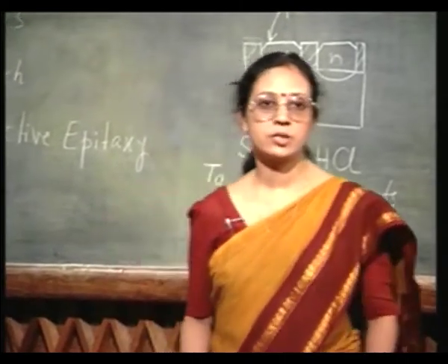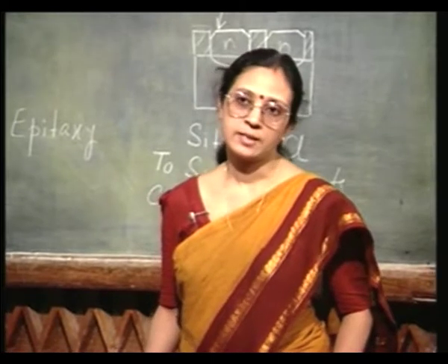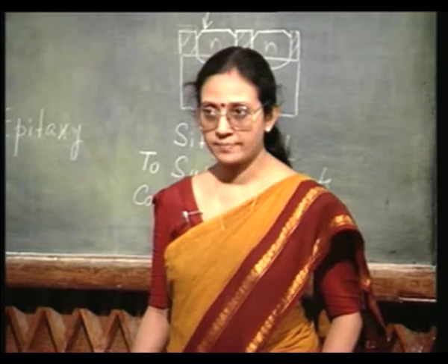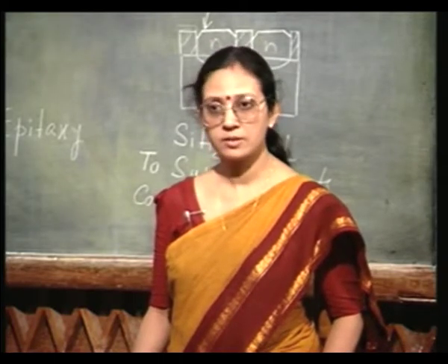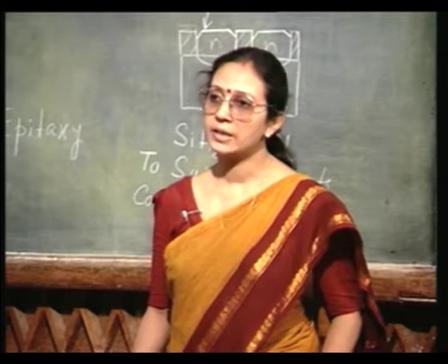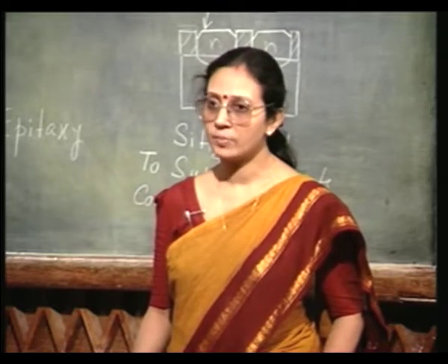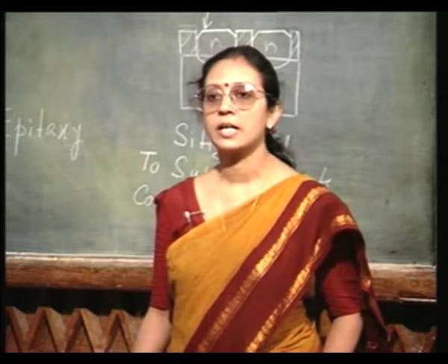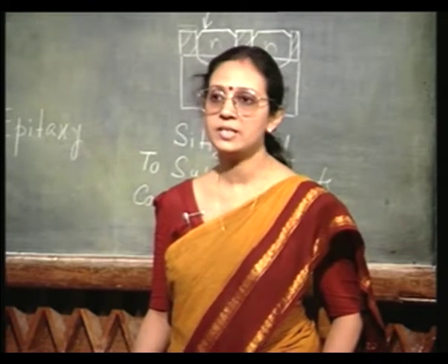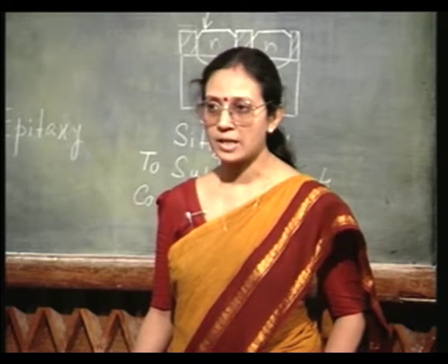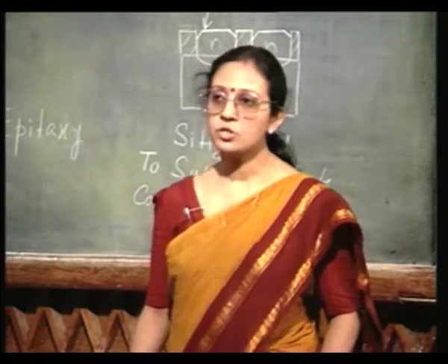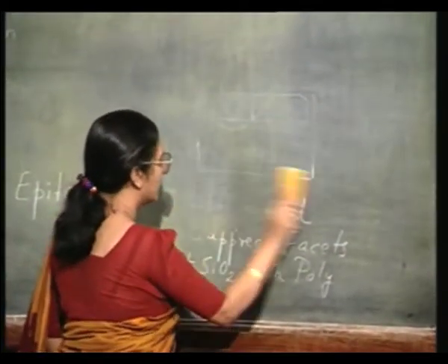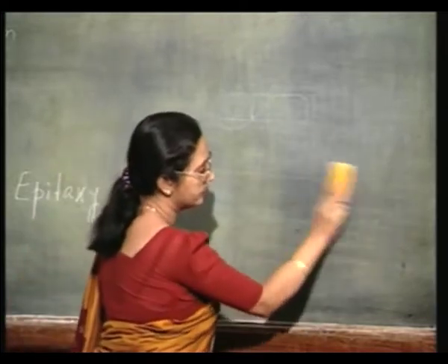After the isolation step, the next step in bipolar junction transistor fabrication is the base. We must have the base region. We already have the buried layer for the collector, we already have the epitaxial region, and then we have the isolation, and now is the time to have the base region defined in the epitaxial area. So, this is the next processing step that we are going to discuss, the question of base doping.